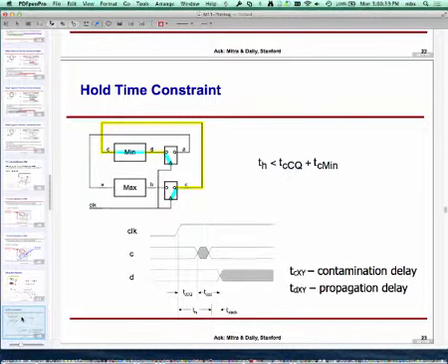So this hold time stuff is actually particularly nasty. You better make sure that your chip doesn't have a hold time violation before shipping it out, because if it does, it's not like the first one, where if it doesn't work, I will live with a slower clock. Here it's not going to help you because it's independent of the clock. The other observation made here is that if hold time is negative, then this constraint is guaranteed to be satisfied. The problem is that if hold time is negative, then setup time would be more positive, so you will have a slower design than normal. So the strategy of artificially making hold time very negative can result in a very inefficiently slow design.